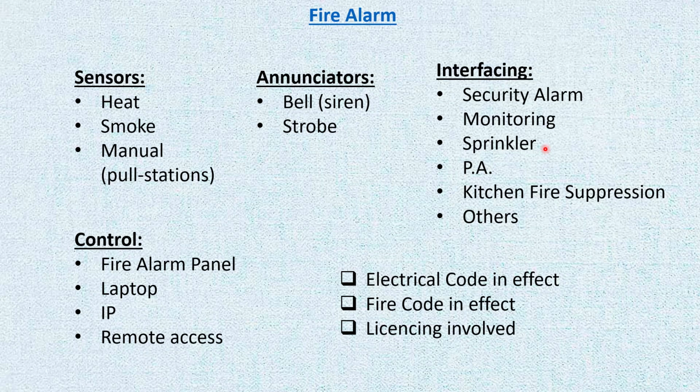When the water starts coming out of one of the sprinklers, of course, the pressure in the whole system is going to drop. And the meter is going to notify the annunciator. The annunciator is going to trigger maybe some things that are connected to the security alarm or the fire alarm, or it's going to have a dialer on its own to dial the monitoring station. So that's a wet system.